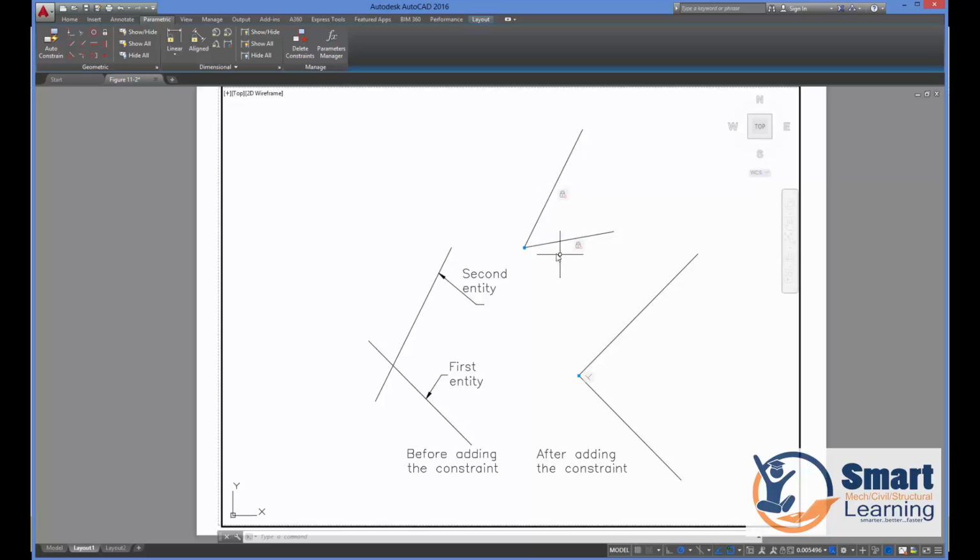So for locking the locations without knowing the horizontal, vertical, or angular locations, you can lock, and later on you can apply them. Suppose you go for an angular one here. Here you can see the angular, and if you apply this here, you can see this is the typical 53 degrees. If you try to change this to, let us say, 60, that will be automatically updated, because with respect to the locked location you can assign a new dimensional constraint to resize and reshape, but this is locked with respect to this object. This is what I was trying to convey.